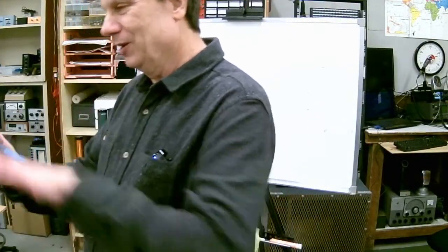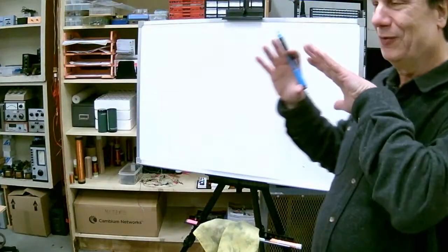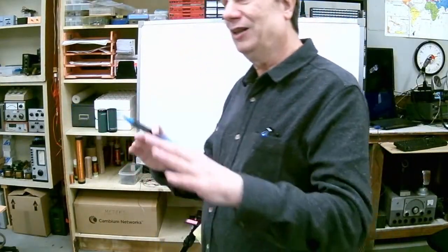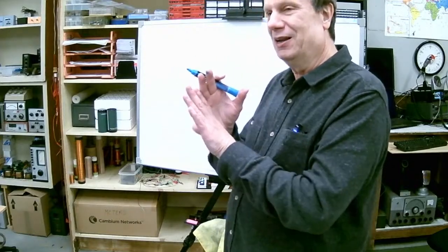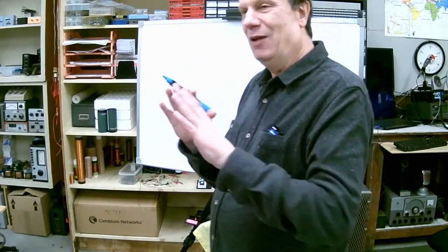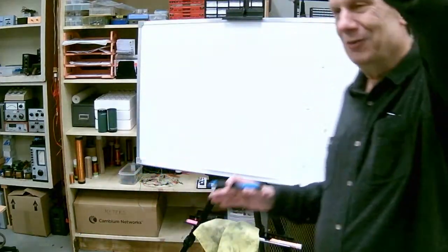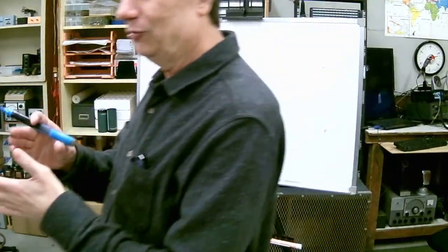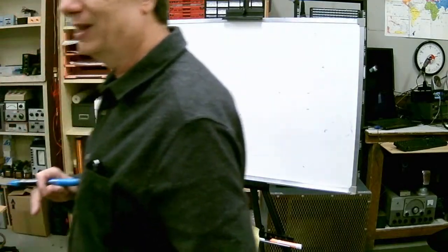If we look at this radiating, expanding wavefront farther away, the percentage of it that you can absorb with a given wavelength antenna keeps decreasing. If we made the antenna proportional to the surface area, it would get very huge as it moves further away. But there is an effective number called capture area, which is the effective size of your antenna relative to the surface of the wavefront.